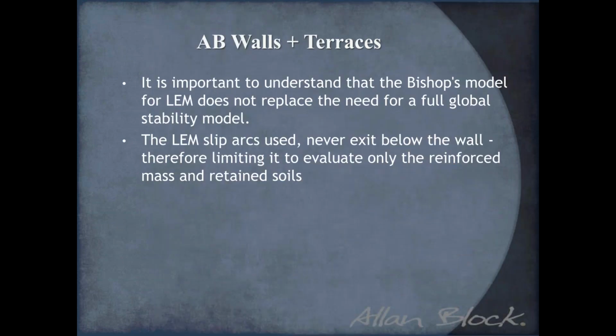So I'm going to stop just for a second and just remind everybody, just like years past, if you're familiar with the internal compound stability that Alan Block and the National Concrete Masonry Association introduced back in 2007, it's very important to understand that the Bishop's model for limit equilibrium and the ICS calculations, they do not replace the need for a full global stability analysis.